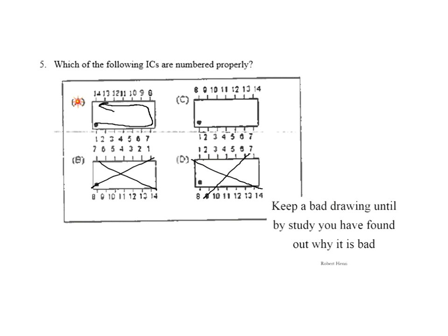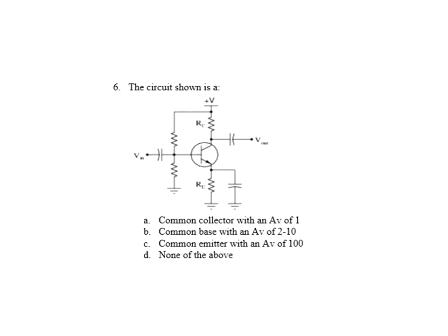Okay. Again, these are really, really easy questions. You don't want to miss these. These are the ones that will knock you right out of the running. Oh my, look, here's another amplifier circuit. Huh, I wonder what this is. Well, I can see it's voltage divider bias. I can see that it's class A. There's one transistor conducting everything. But I do not have any information there telling me that it's a certain kind of common type circuit.